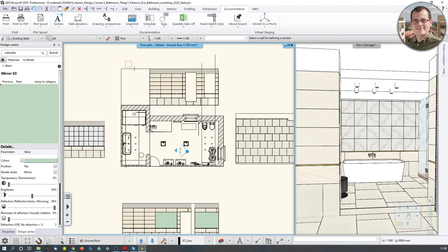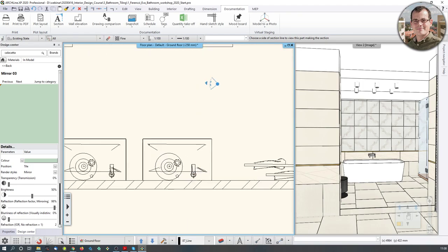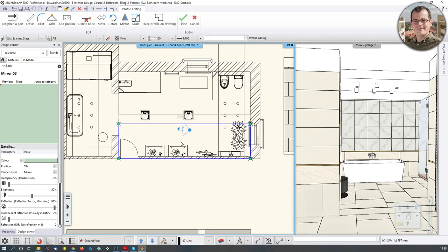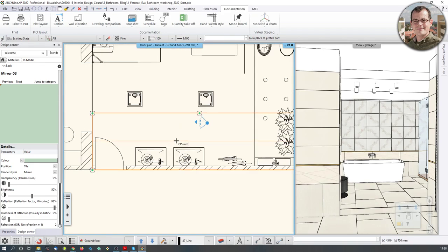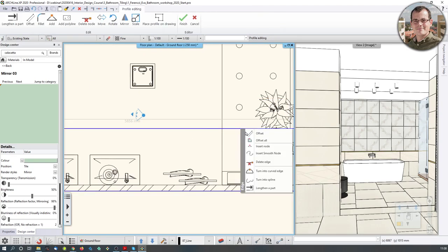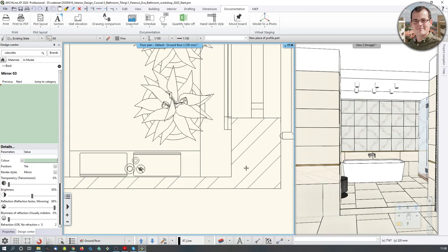We are going to go with image, and click on the wall that you want to get a wall view of. So just click on the wall, and now the software tells you, okay, which direction you want to look at it from. I don't know if you see this orange arrow, but you make sure it's pointing from where you are to what you want to see, like that. And then define the width of what you want to see, and the depth. So depth is always good to trim back a bit, because otherwise, for example, I don't want the second plan to be in there. I just want to have the first one. Or if you are inserting a node, then even the second one could be ignored like that. So I don't want to have this very nice plant over here.